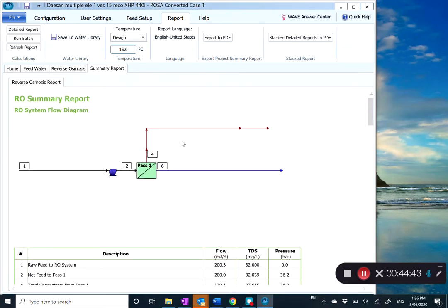So when you design, you can make a smaller size. For example, like a seawater desalination plant, we have 250,000 cubic meter per day. So we don't design 250,000 cubic meter per day in one train. So we divide, let's say, 10 times.